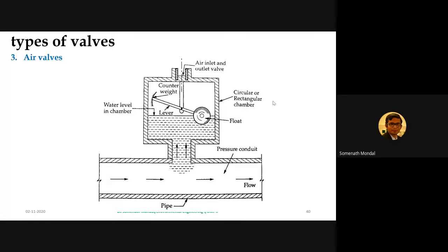Okay, so basically what we are showing here is the air relief valves. The main idea is that the air which gets interrupted because of the discontinuation in the flow needs to be taken out from the main pipelines. That is the main objective. During the flow under pressure, there is a tank which is attached, and within the tank the air relief valves will be placed.